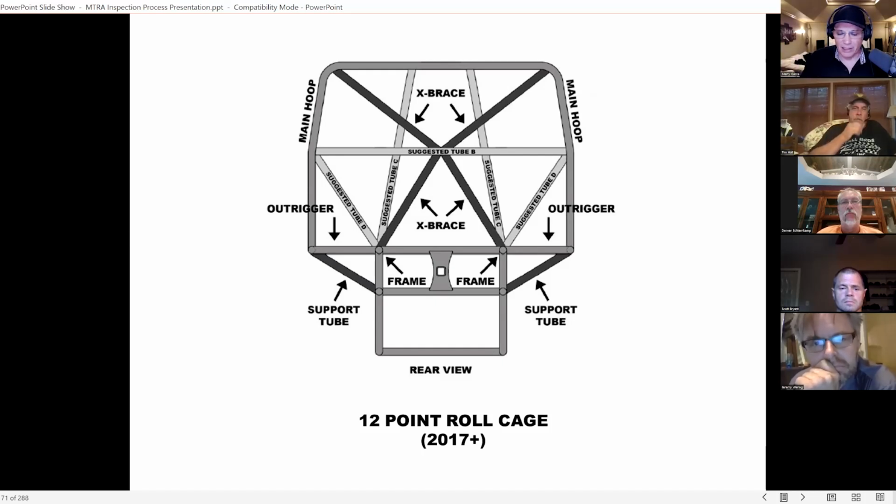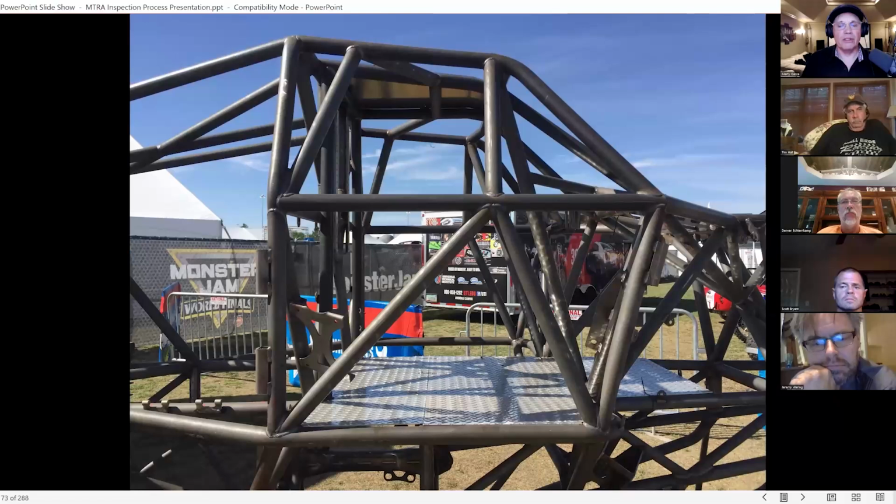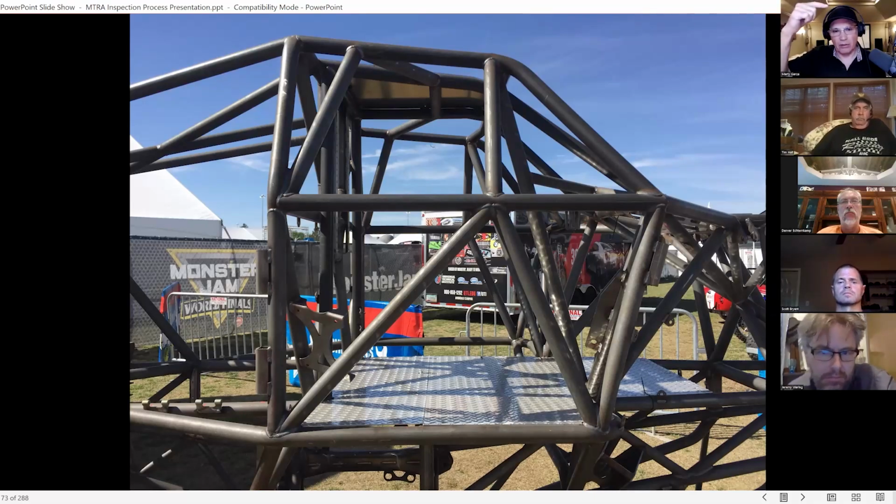And this is getting into the weeds a little bit on design, but you want to be conscious of watching the way some of the trucks are building their upper halos. There's different ways. Let me get you a picture where you can see it. Okay, you see that what would be like the A-pillar tube in this case curves and bends up and connects to the main cage, or a main down hoop. Some guys will do a halo tube with a separate piece attached there.